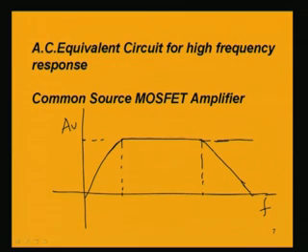And we know that there is the 3 dB frequency, which is a very important one, and that is when the gain drops off to 1/√2 times the mid band gain. We get lower 3 dB and higher 3 dB frequencies, these two being the cutoff frequencies, and all these considerations we have already discussed while discussing the BJT. So, similar characteristics we will be obtaining here.